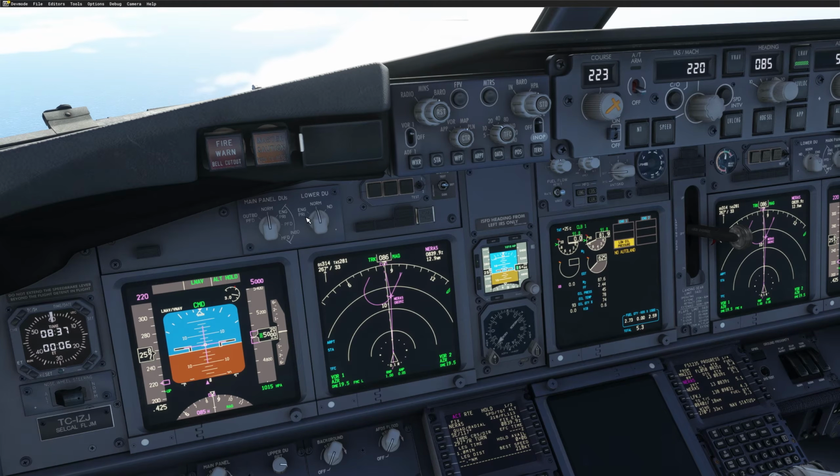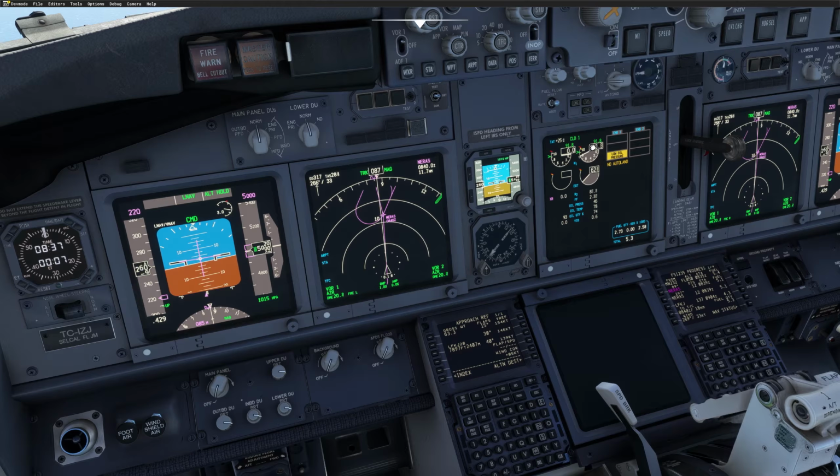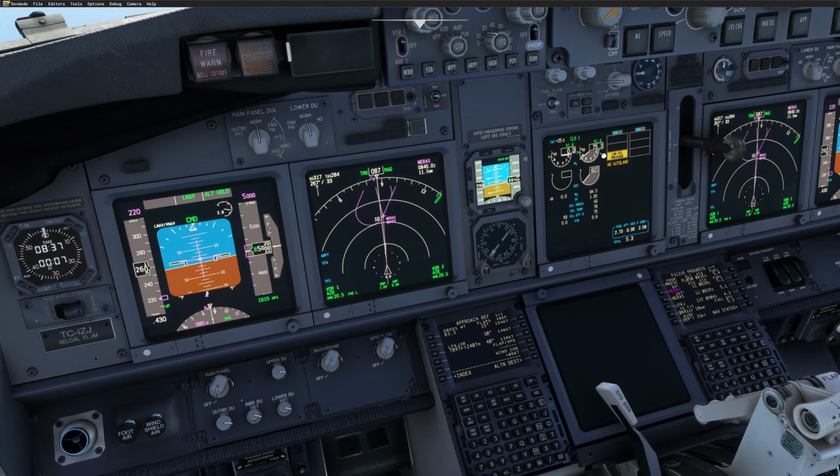And here we go. Alright, what I wanted to tell you just before ATC came is if you look at the weight of the aircraft, now 63.3 in kilograms, and you add about 10 to these figures, so 73. If I set my N1 to 73, so 10 more than the numbers here, that will be a very nice setting to have a speed above minimum speed, and that setting will work all the way to your configuration for landing. So now what we have to do in order for the aircraft to turn perfectly well in the holding is to trim it properly.